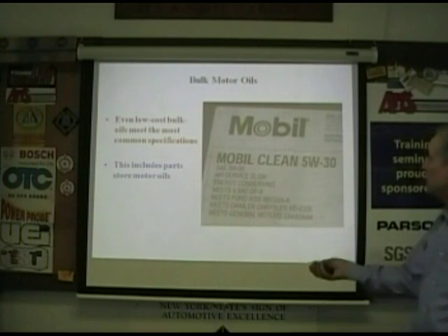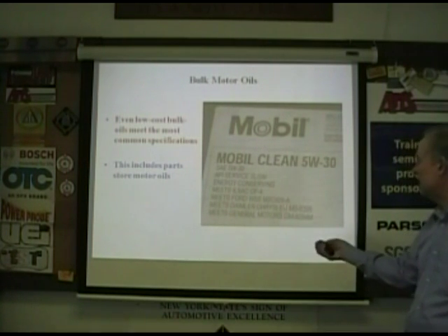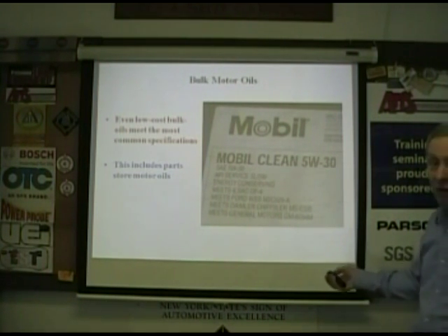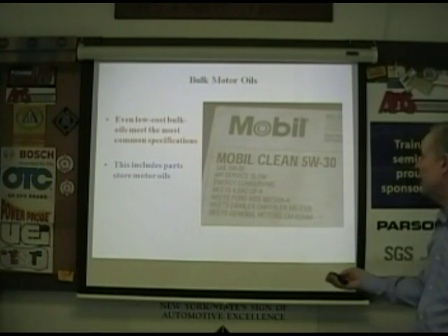This one here, if you look at this tag here, it says 5W30 SAE, API up to SM, energy conserving, ILSAC GF4, there's a Ford spec there, WSS-M2C929-A, Daimler Chrysler in this case, and GM, this 6094 spec. So it meets all of those. But again, you don't see a VW or you don't see a Mercedes. You don't see those specs on here. BMW, you don't see any of that on there.